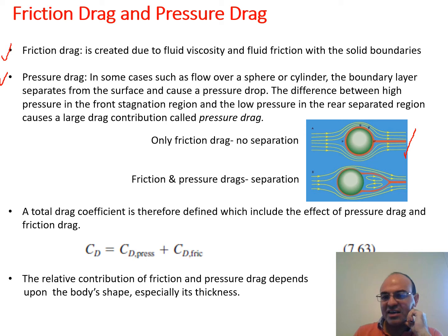So you see that on the surface, you can imagine a friction created if, for instance, we consider viscous flow at very low Reynolds number, where the streamlines and flow field remain symmetrical. If this happens in reality, the drag force would be only because of friction, because you see no separation of the boundary layer from the boundaries. However, the second one is reality.